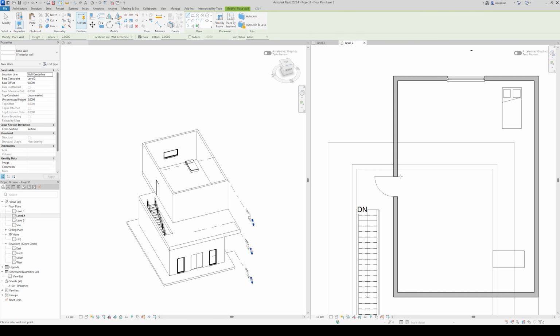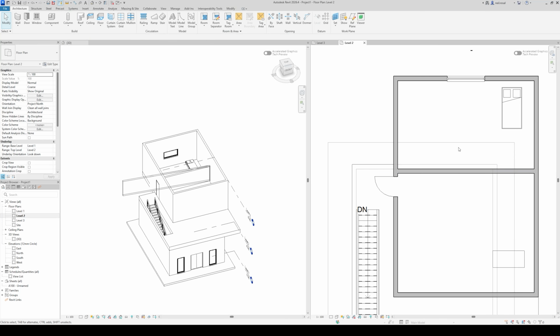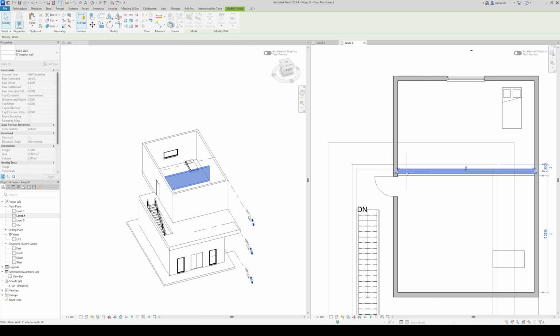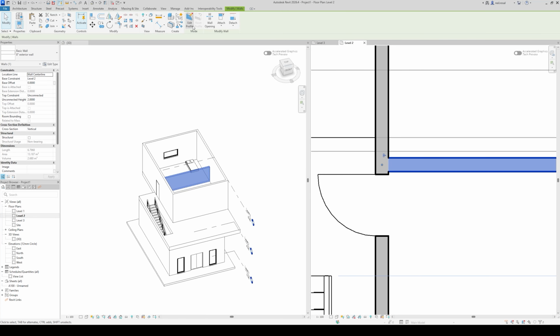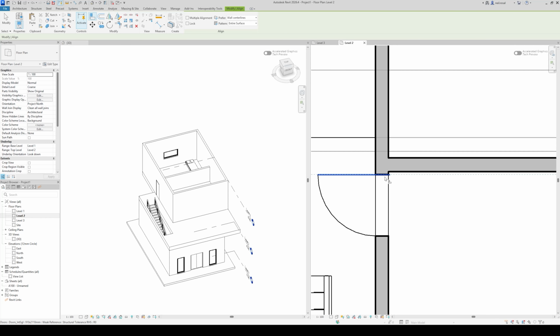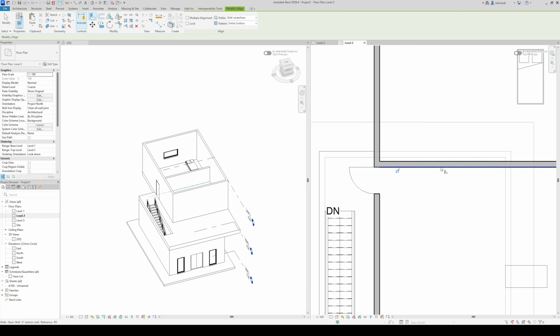to the wall. Actually, I want to use the align tool. Sometimes it's hard to snap it into place, like that edge. So what I use is the align tool when we select our wall, which is this tool, I believe, right here above the move icon. It's in the controls. You set the boundary where it wants to be aligned, and you can just move the line of the walls to whatever that boundary is.